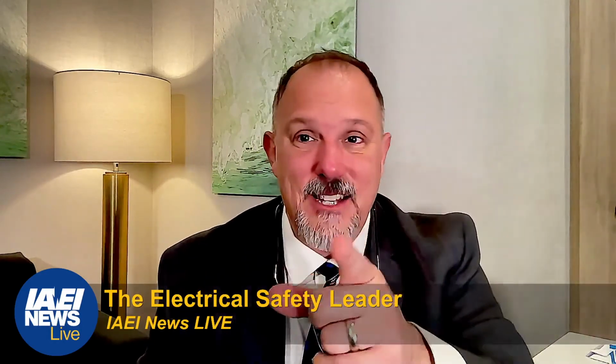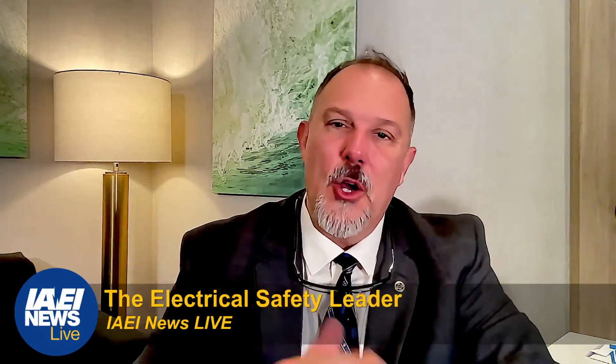And what provides all of the protection when it goes off is the upstream main overcurrent protective device. That's the device that is going to ignore all those settings and trip without an intentional delay, which means what? Probably around 0.07 second clearing time, somewhere in that ballpark, which is a heck of a lot better than 30 cycles. A heck of a lot better than 30 cycles. That is what zone selective interlocking is there for. That's what it does for you.